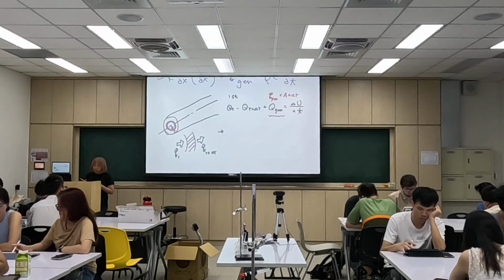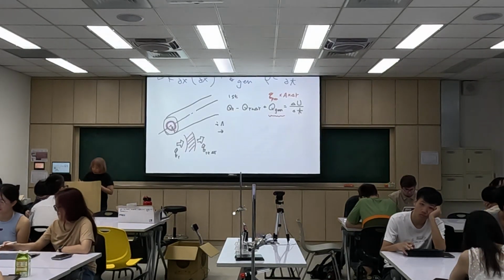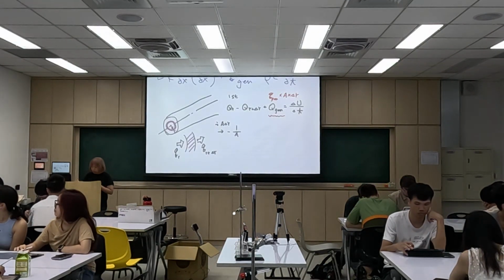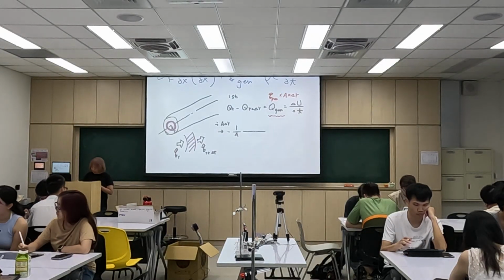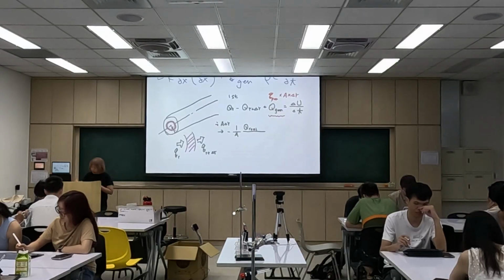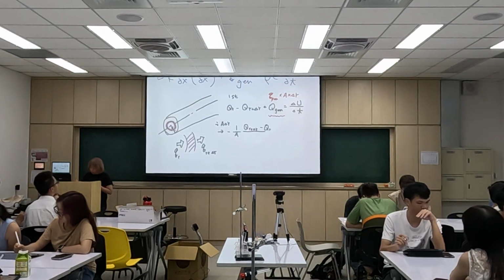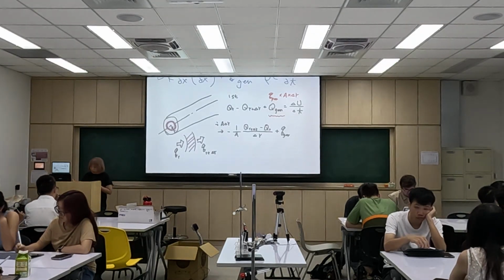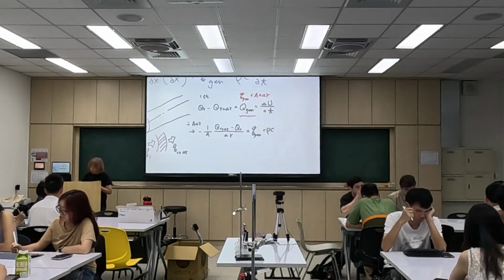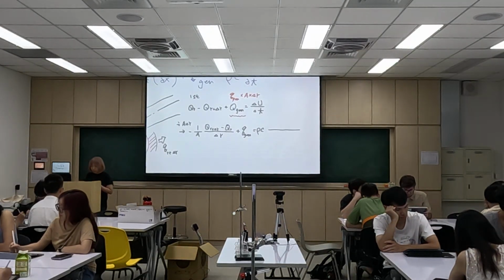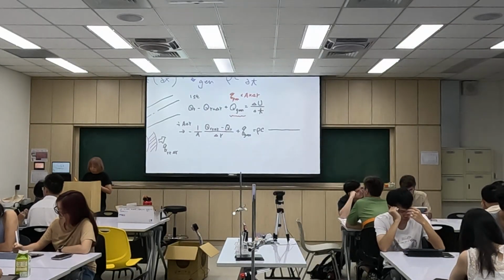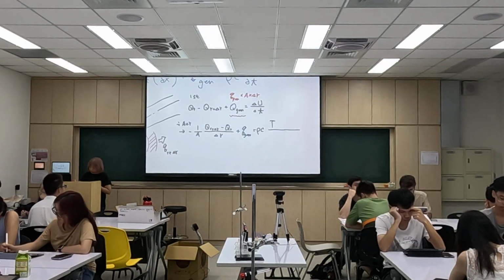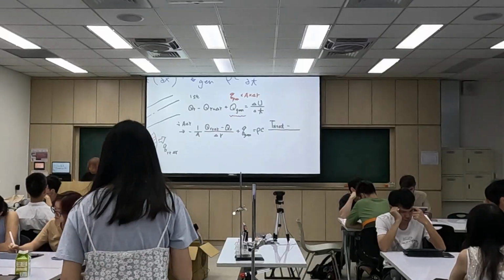So we divide our first equation by the area and the delta r, so you can see, then we put the minus in the front, then it will be easier to put the Q at r plus delta r to the front, and Qr, then this will become Q generation and rho C, T at t plus delta t minus T at t.